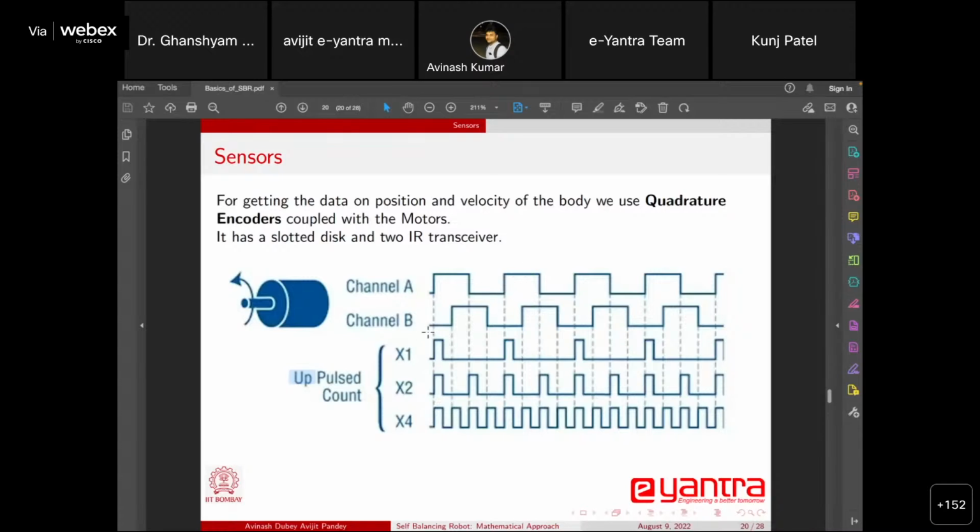So there are two optical sensors, and every time a slot passes, two pulses will be generated through two different optical sensors. These pulses are received on different channels, channel A and channel B. What you can clearly observe here is that they are not in phase with each other.